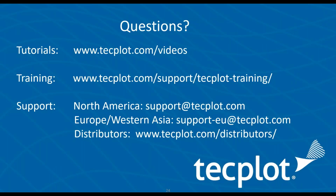Sorry, I had an audio connection lost for a second there. I hope you heard me. So the second part of your question is cost, and the cost is going to be higher, but in general, higher per cell, because it has to do a solution of a nonlinear system of equations, especially if you have nonlinear geometry. It will have to solve a system of nonlinear equations to do the interpolation.